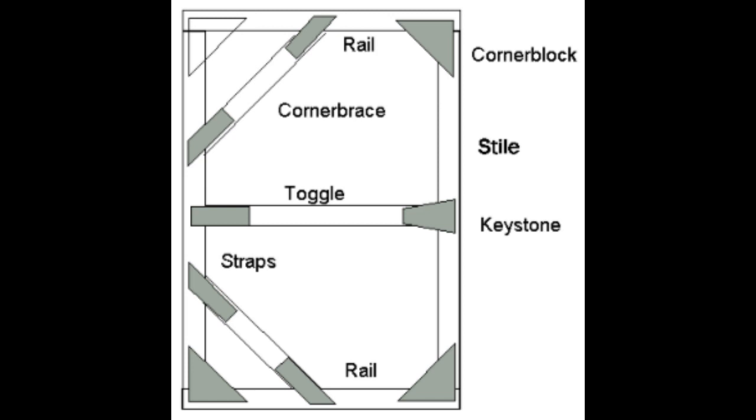You'll notice, however, also in this picture that there is a slight gap around the edge of the frame. The reason for this is there are often times in which you can have multiple Broadway style flats in conjunction or next to one another. So every time that you build one, you want to ensure that there's at least a 3/4 of an inch gap around each one. That allows the framing of one to actually butt up and create a perfect corner or almost seamless corner.